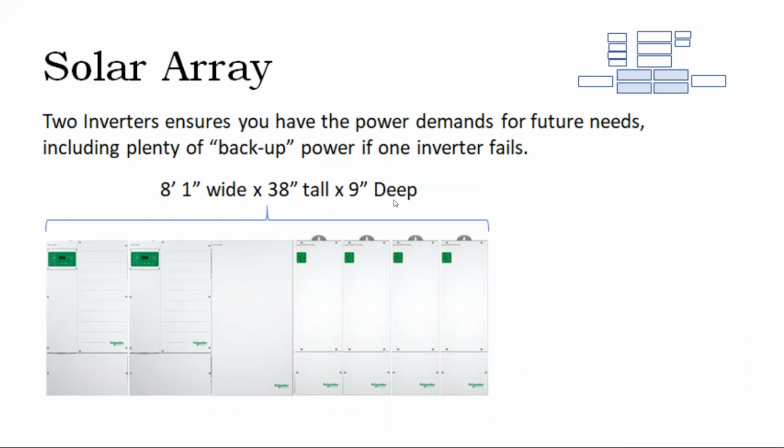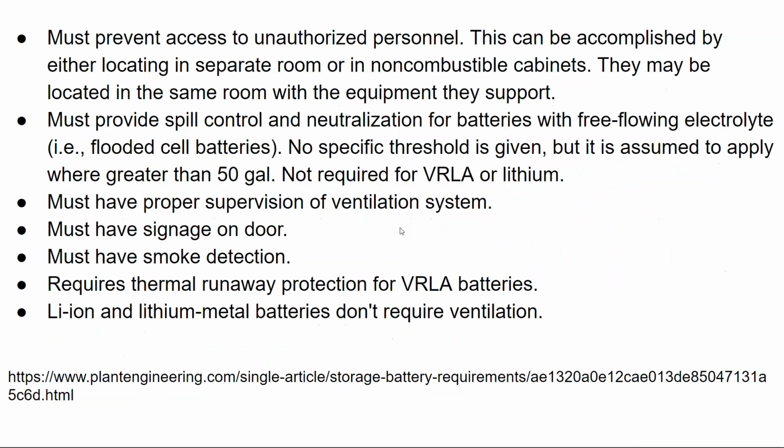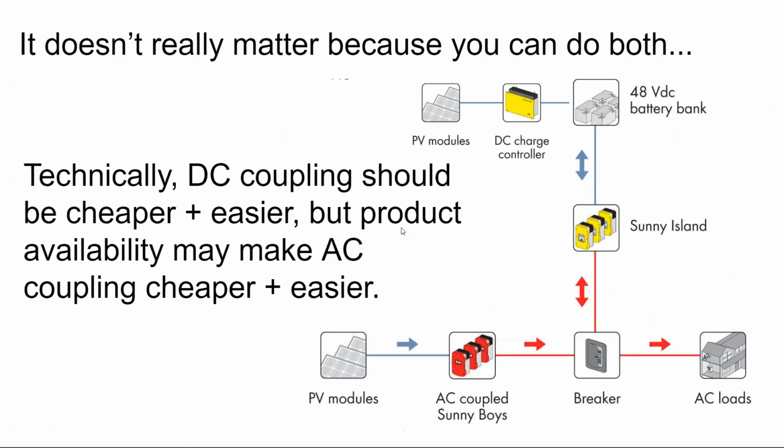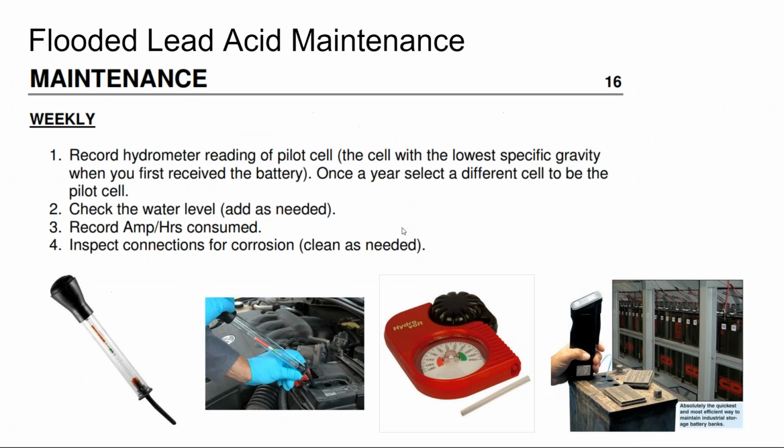Furthermore, especially if you're going into double redundant systems with multiple charge controllers, just keep in mind that not only do you have to have space for your solar inverter or charge controller, but then you also have to have the space for your battery inverter. I don't think we really got into the nuance between the difference between a solar inverter and a battery inverter.